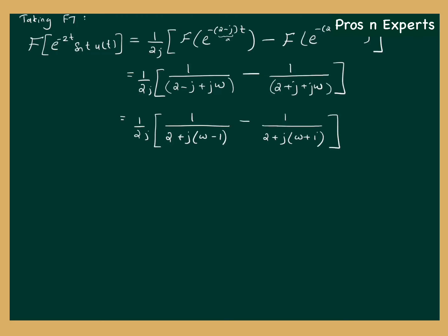What is the Fourier transform of minus j t x of t? If X of omega is the Fourier transform of x of t, what is the Fourier transform of minus j into t into x of t? It is nothing but d by d omega of X of omega. It is the frequency differentiation property of the Fourier transform.